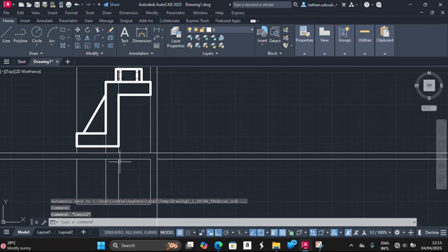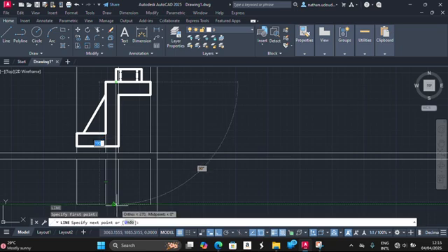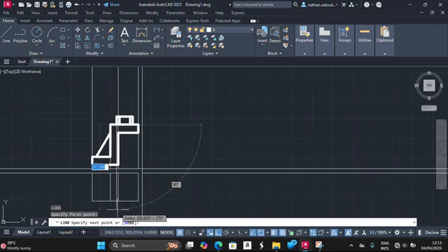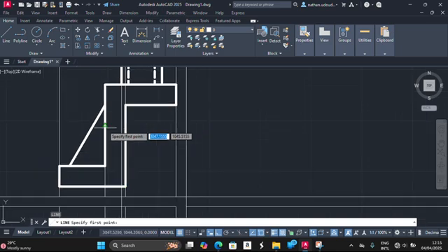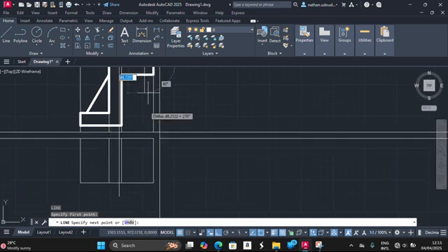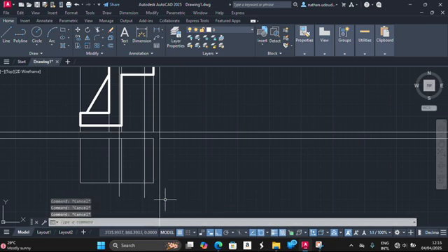So now, in order to draw this, L, enter, can trace, can pick up from this. It comes like this. So that's the circle. We're trying to draw the plan. Okay, so L, enter again. That will be from this point, and then we draw it downward.